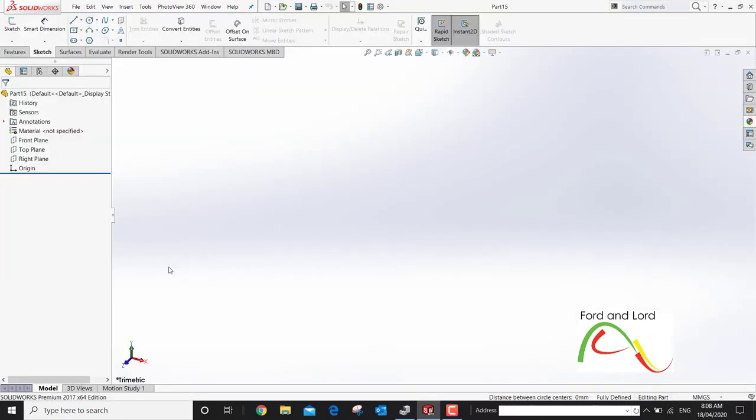We will start with the sketch for the wooden casing of the pencil. In terms of SolidWorks, a pencil is a multi-body part. A multi-body part consists of multiple solid bodies that are not dynamic, meaning different parts of the object do not move. A pencil, at minimum, consists of 2 bodies, a wooden casing and a lead. Although pencils can have more than 2 bodies, such as an eraser, as a fair rule, we will design a simple pencil with just 2 body parts, namely casing and lead.